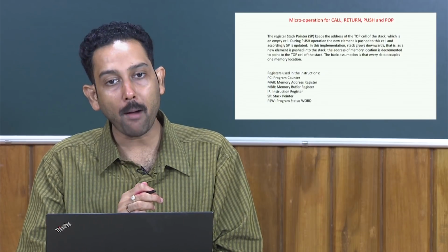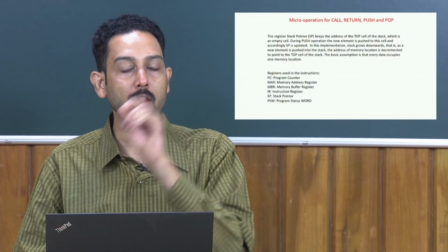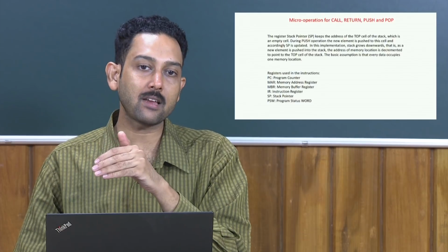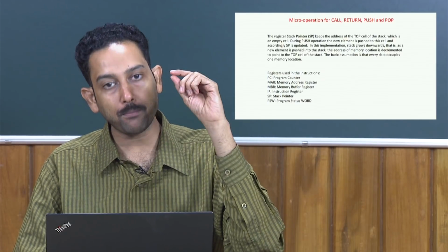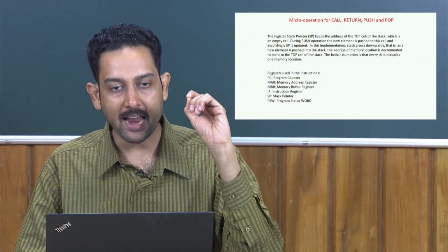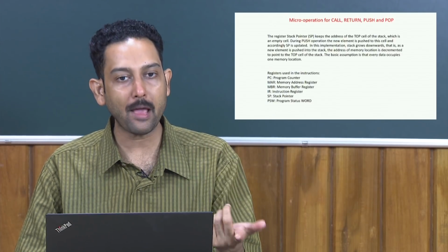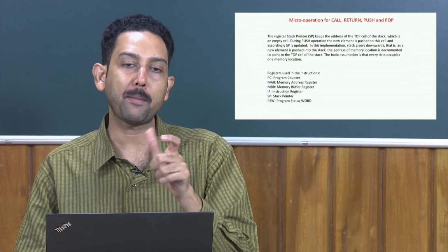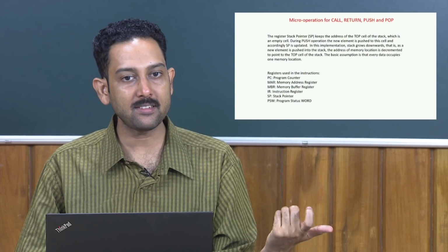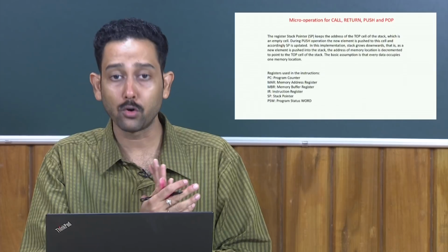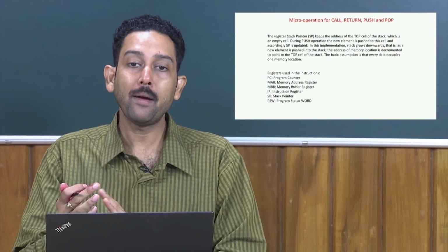Again, here pop means the stack pointer value will be loaded to the address register, then the address register will point to the memory address which has the corresponding value for the stack entry which I want to pop. That value of the memory will go to the memory data register and that will go to the instruction register and so forth. So, in fact, push, pop, call and return.